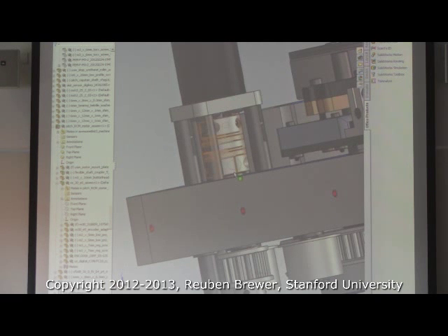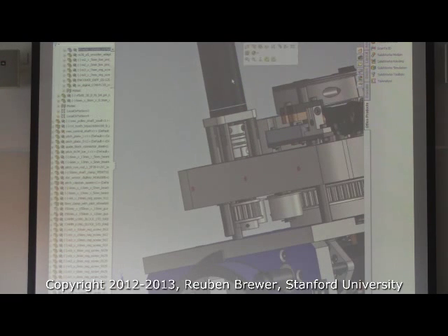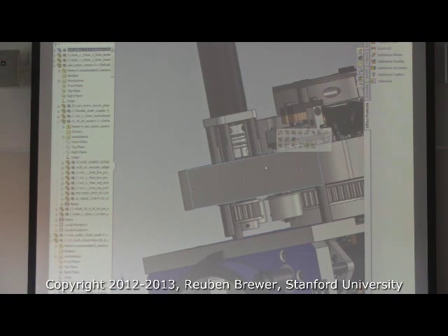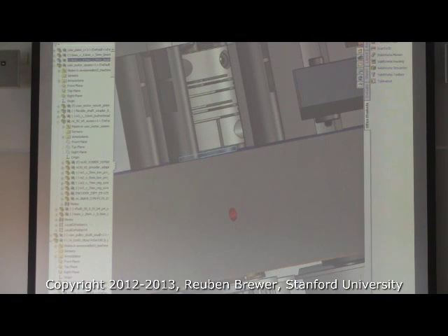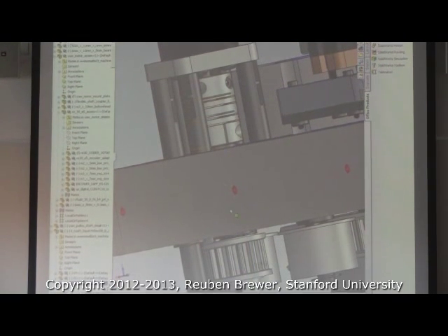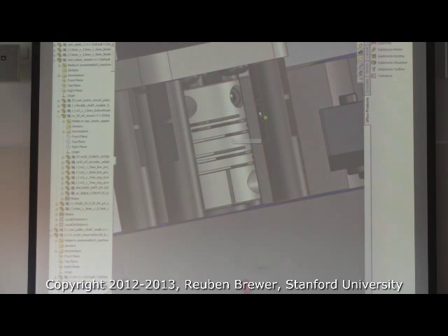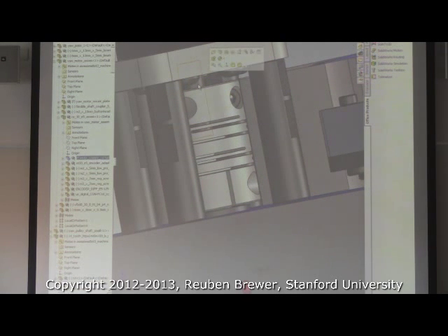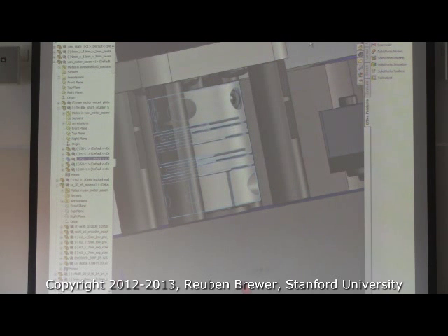Okay, so here's my motor. Here's the pulley I want to drive. Here's the plate all of this gets bolted to. I have one bearing, two bearing. So the shaft of this pulley is supported on the bearings, and then I'm connecting torsionally the motor shaft to the shaft through this flexible coupler. Someone tell me why. Why don't I just put the pulley directly on the motor shaft?